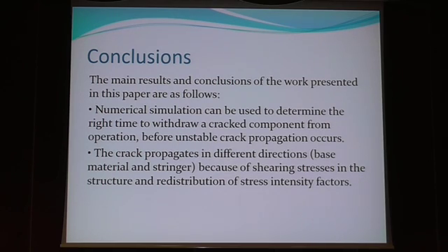The other one, which was actually more important for us, at least from the point of view of numerical simulation, is that the crack propagates in different directions, base material and stiffener. This is due to shearing stress and redistribution of the stress intensity factor. Thank you.